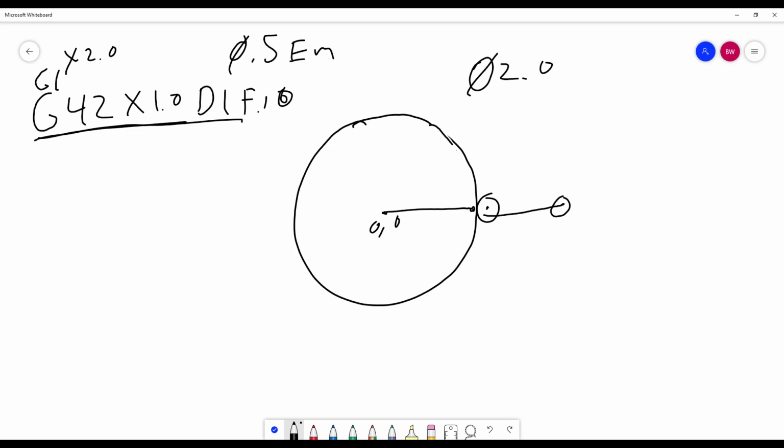Now we've got to start turning. So we need to go counterclockwise, so we're going to use a G03 for the movement. And then with these lines of code, we need where we're going, X and Y. So where we're going here, we're also going to need some information on the swing point. Let me actually redraw this a little bit more compressed here. So we're going to go G3, X, Y. We're also going to need an I and a J. Now, you can use an R function, but we're going to focus on I's and J's for these examples.